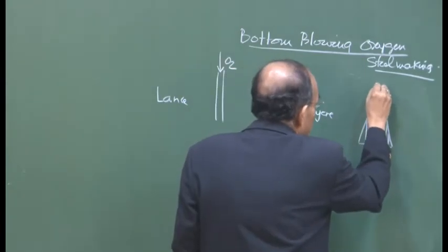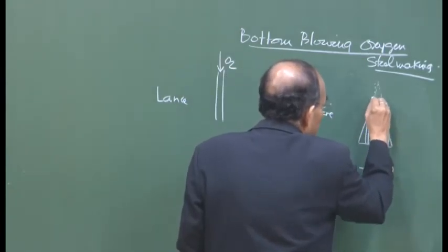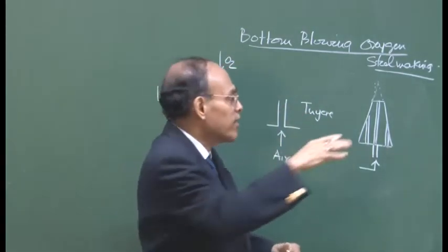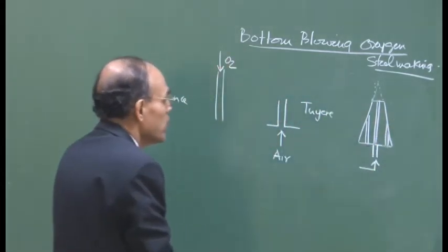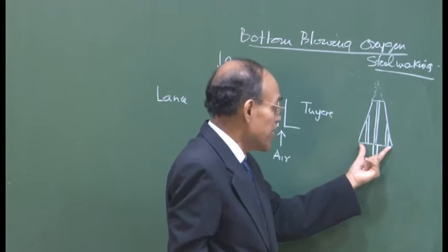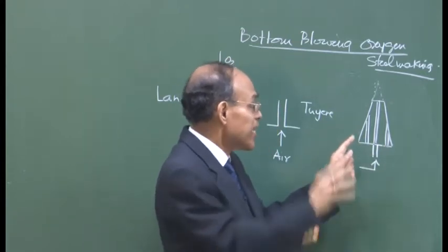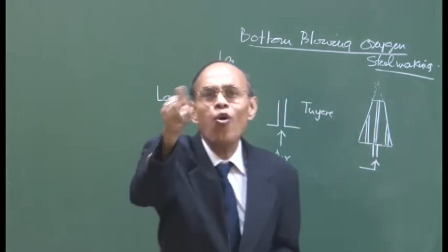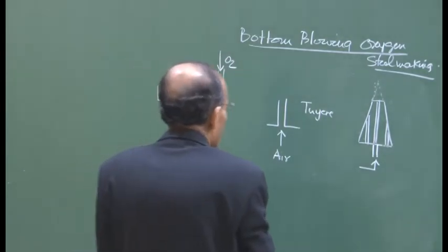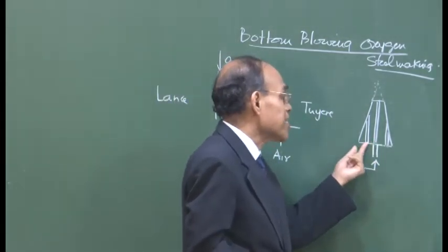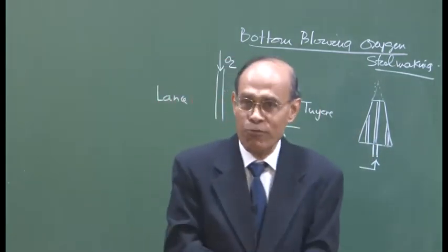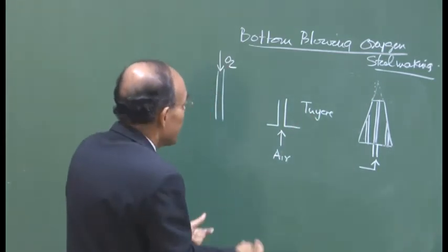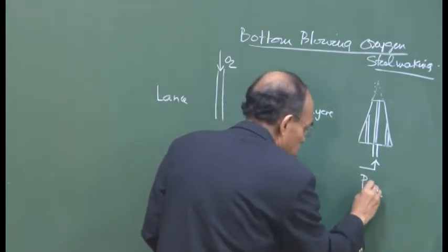So, typically, if you draw it like this, where this part does not exist, then this is actually a solid cone, and then it is truncated, the top is removed. So, there could be vertical slits through which gas is going to travel, or there could be interconnected micropores through which the gas can pass. These gas injection passages are introduced during the period that they are fabricated. These are straight vertical tubes, tuyeres, and this is porous.